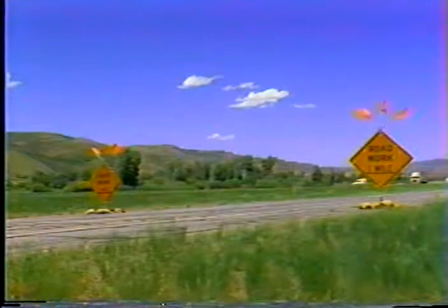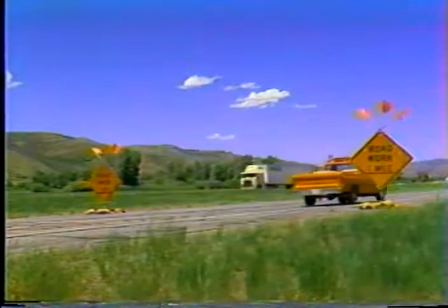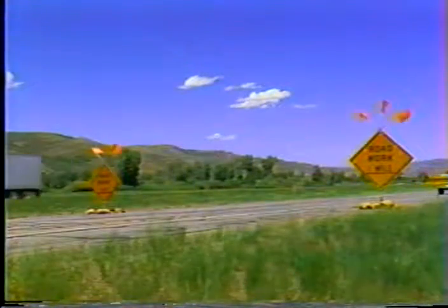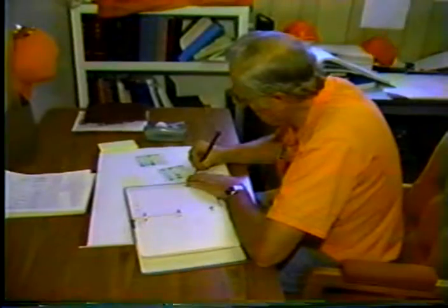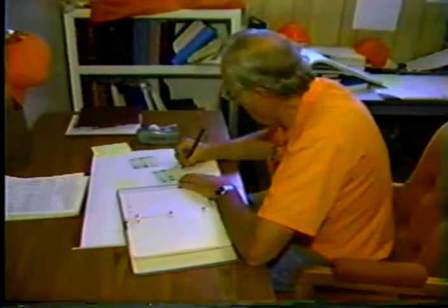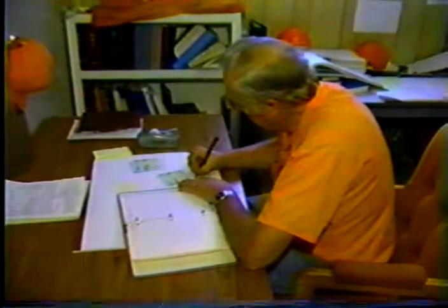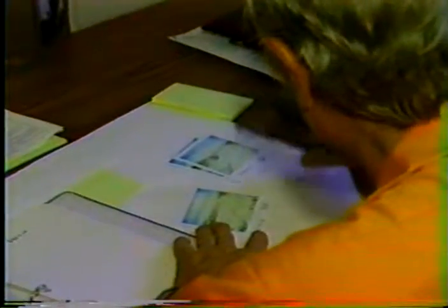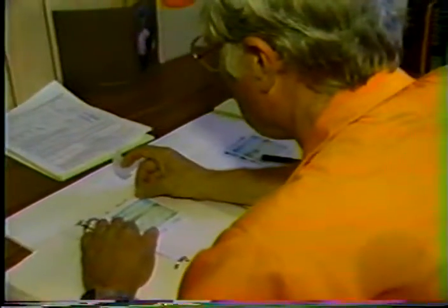In the event that your agency is called on to defend itself due to a work zone accident or injury, your records may represent the only way you can reconstruct the conditions of the worksite on a particular date and time. Your daily record should document all traffic control activities and problems that occurred on the project. Include dates, times, weather conditions, and so on. Use photographs, drawings, and diagrams to clarify your reports.